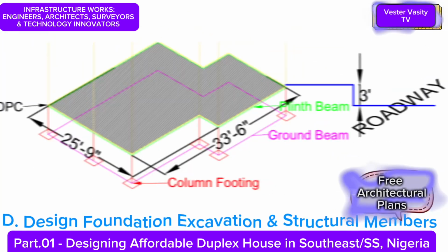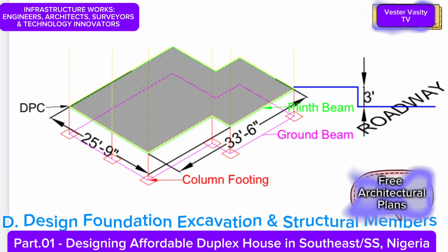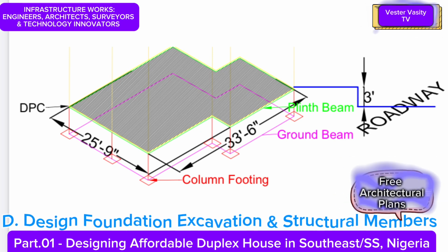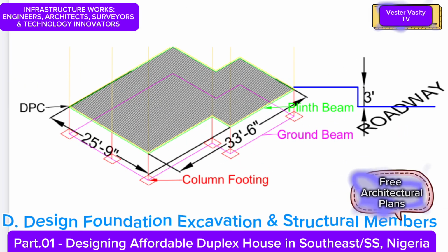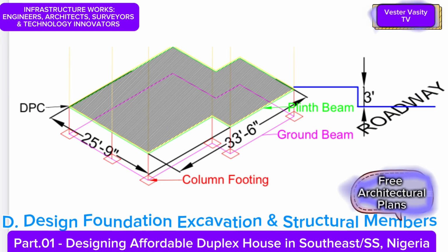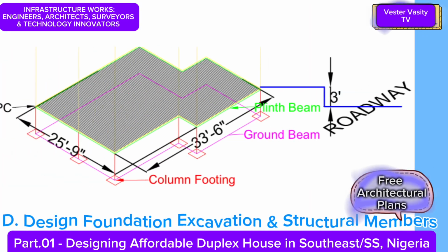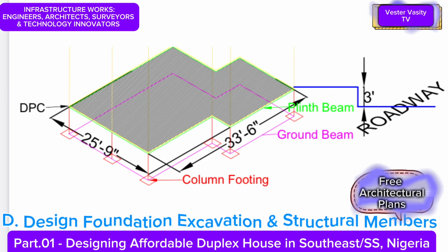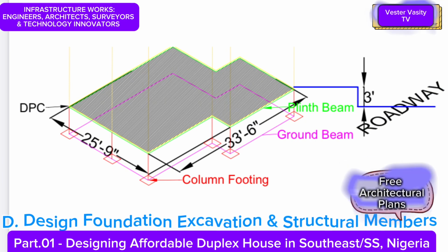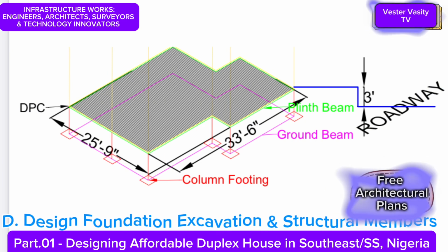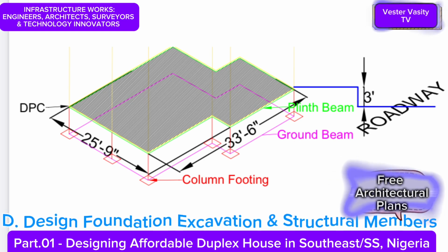The ground level of the duplex house is recommended to be designed and constructed 3 feet above the adjacent roadway centerline profile to keep the duplex house from flooding from the rain or stormwater from the roadway gutter or nearby drainage facilities. Again, raising the ground floor level about 3 feet above the roadway centerline profile will keep roadway rain or stormwater from entering or flooding the duplex house.